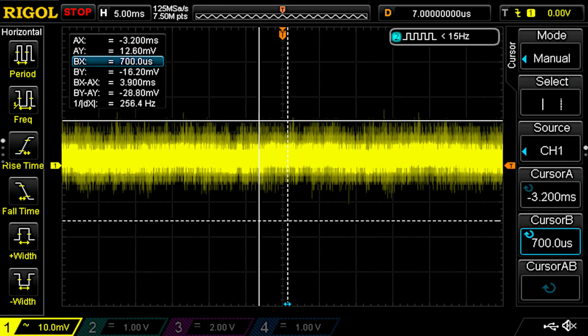But the ADC in the microprocessor is not referenced to digital ground. It has its own ground pin, AVSS, and that ground pin is connected to the analog ground plane. And I have a capacitor very close and right across the analog supply pins to the microprocessor. And this is the waveform right across that capacitor. It is basically the same as if the probe tip was shorted to the ground spring. I think the 3.3 volt analog supply to the ADC is going to be fine.